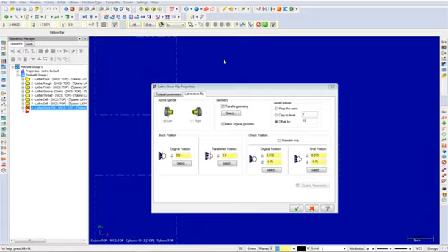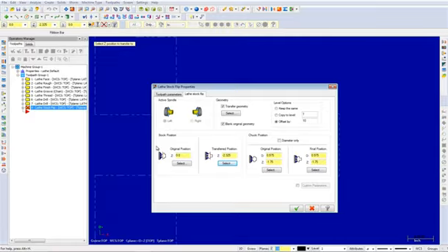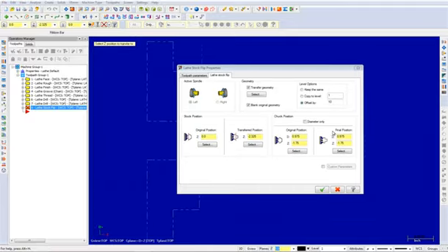Now the Lathe Stock Flip dialog box will reappear. Under Transferred Position, choose the Select button and pick the endpoint as shown. Now input the final position values to specify the new chuck's location. Input the values D equals 0.875 and Z equals negative 1.35.